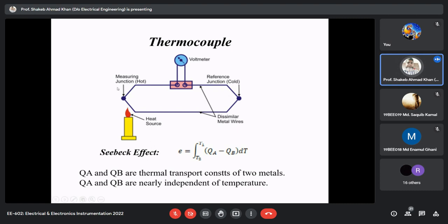In response to the temperature difference in a setup, voltage is generated out of the blue. So this kind of sensor is called an active sensor, unlike the resistive sensors. Over there, if you want to convert the resistance change into voltage, you require a supply and a circuit. Here, that kind of thing is not required.